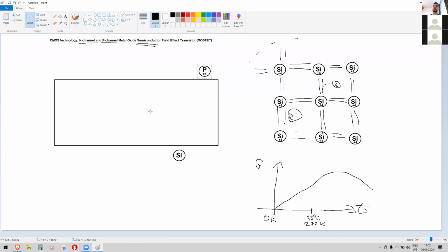The temperature is too low to melt this material, but high enough to make these silicon atoms in the lattice oscillate so much that these phosphorus atoms just jump into some place of silicon. Some silicon moves aside or expands up or sideways, and some phosphorus atoms just randomly fall into this lattice, and they start to pretend that they are silicon, right?